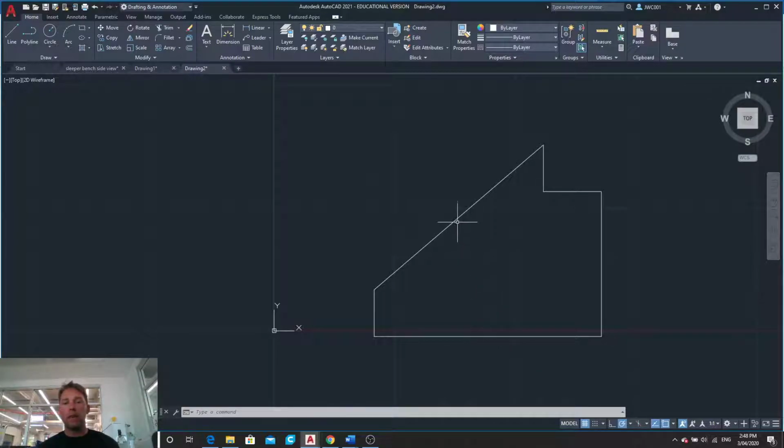At the moment, they are a series of individual lines. Because I wish to copy it and scale it down twice, I need to join those lines. And there's a couple of ways I can do that. I can click and release. I've highlighted all of them. And I can go into modify and select join, and now it's one continuous closed polygon.